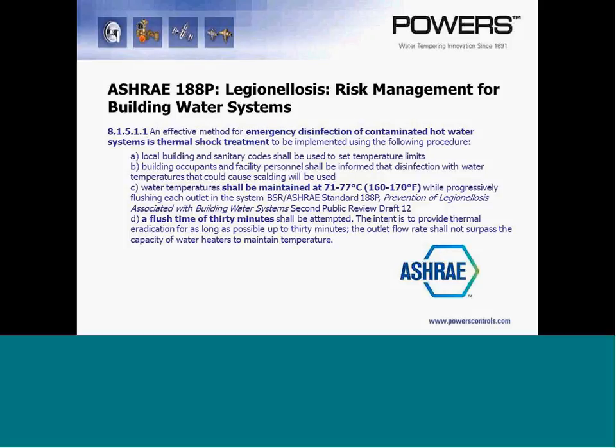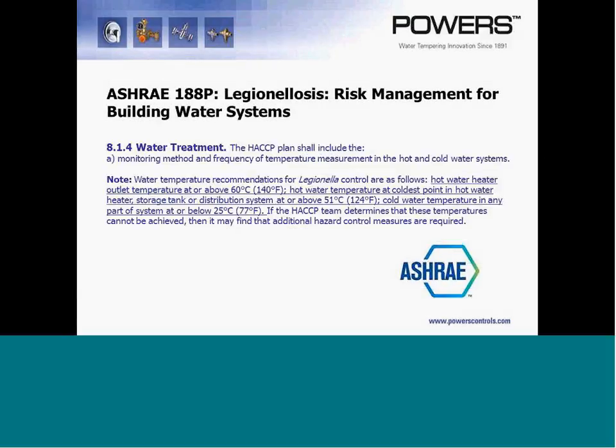And here's some specific language to that. Essentially, it's helping facilities deal with instances of, let's say, a Legionella outbreak within a facility. It talks about hot water sanitization and flushing. That's one of the ways. There are numerous ways, but this is clearly one of the ways to address Legionella or bacteria outbreaks. And this gives some guidelines to facilities on what the protocol should be to address that. And obviously, mixing valves play a key role in minimizing risk to the facility.